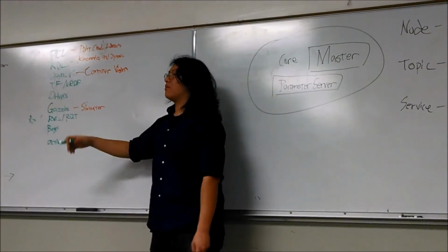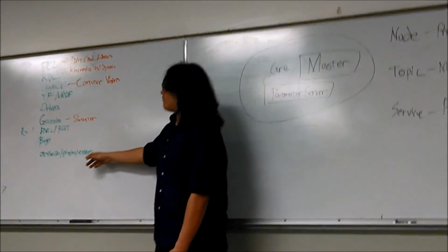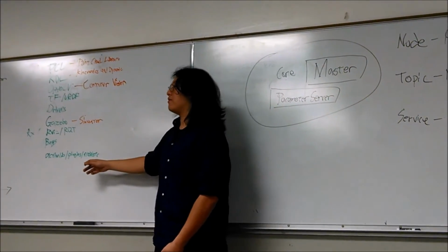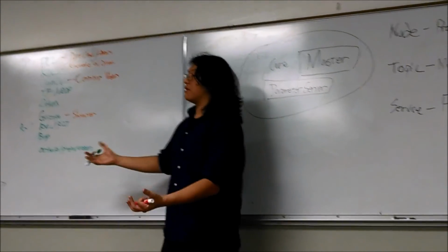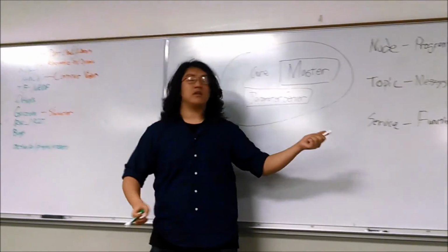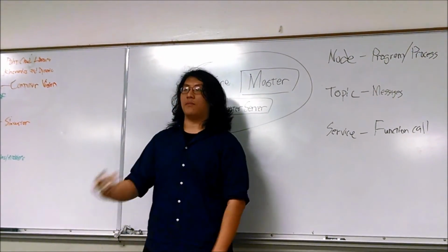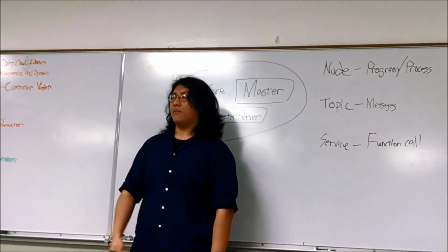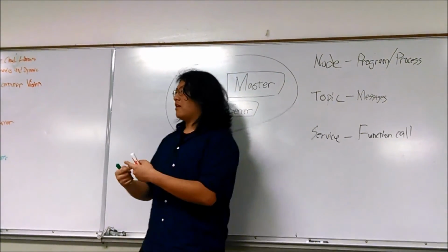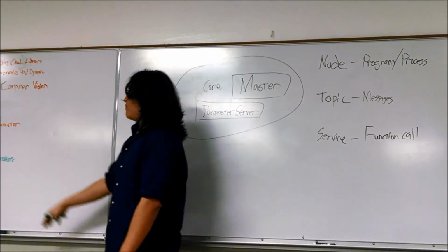This allows for forms of communication between nodelets that have a lot less overhead than topics and services. Topics and services have to talk to each other by opening up TCP or UDP pipes between them, and this causes a lot of operating system overhead underneath.